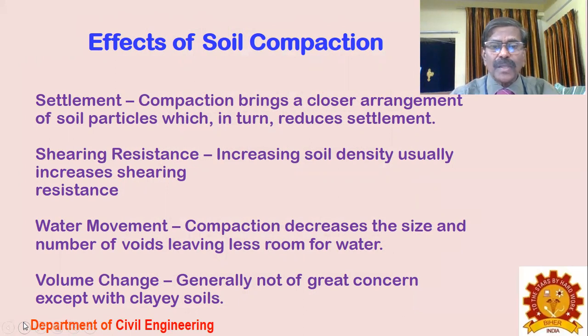Then water movement. Compaction decreases the number of voids in the soil, leaving less room for the water. Then volume changes, generally not of great concern except with clay soils. Sometimes because of water content fluctuations, the clay soil behavior will be different. Volume changes will be there. The shrinkage limit will be exceeded, and compaction will be very less. All those things will affect the engineering properties of the soil.